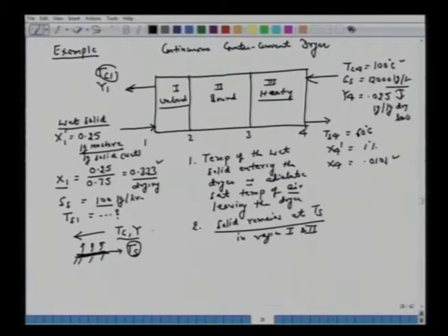Alright, so under steady state we have the surface temperature as adiabatic saturation temperature, or this could be wet bulb temperature. We talked about this. If you neglect the radiation effect or conduction effect, then the surface temperature will be wet bulb temperature. Otherwise it reaches the adiabatic saturation temperature corresponding to this air quality. So that's very important that we understand here.